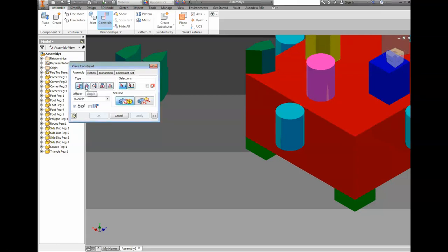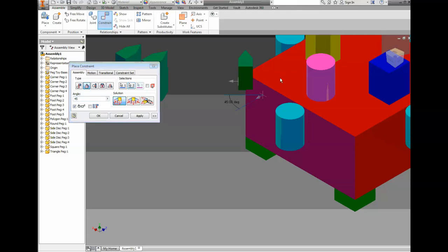So how to put down an angle constraint? Well, once I selected it, there's 3 options. You're not ready for the 2 on the right. They're pretty difficult and pretty hard to work with. Go ahead and use the one that says directed angle, the one on the left. The one that has 2, that we only have to work with 2 faces. And I'm just going to select 2 faces, and I'm going to tell them to be 45 degrees apart from each other. Now, sometimes when you do it, depending on which face you selected first, it'll go in or out.